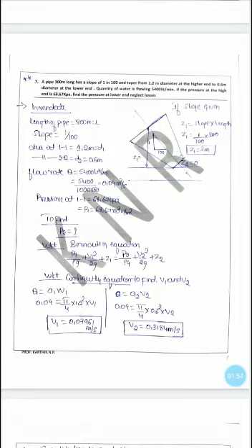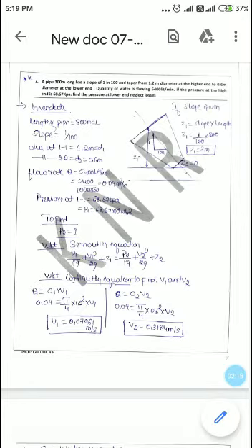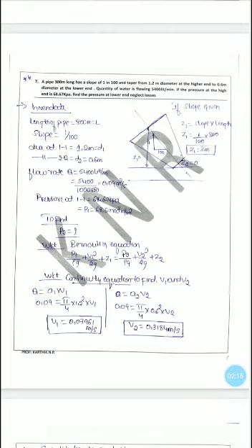Then write down the given data: length of the pipe is 300 meter, slope is 1 by 100, diameter at section 1 is 1.2 meter, diameter at section 2 is 0.6 meter. Flow rate Q is equal to 5,400 divided by 1000, then minutes to seconds, again divided by 60, that is 1000 divided by 1000 into 60, which comes to 0.09 meter cube per second. Then pressure at section 1 is 68.67 kilopascal, that is 68.67 into 10 raised to 3 Newton per meter square.